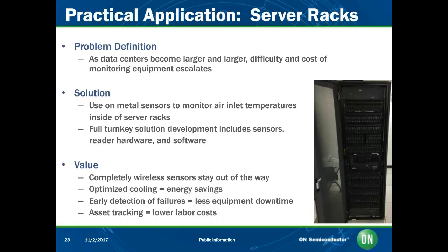Right now, servers can tell you the temperature of their processors, but if you get a server that has a processor that's hot, you don't know why. It could be hot because the air inlet temperature is too high. It could be hot because the intake fan is not working. It could be hot because there's too much load on that processor. You really can't tell. So with more data using our smart passive sensors, you can do some correlation to air inlet temperature, outlet temperatures, et cetera, to get a real, complete heat map of the whole system to see what's going on. And also, again, look for trending.